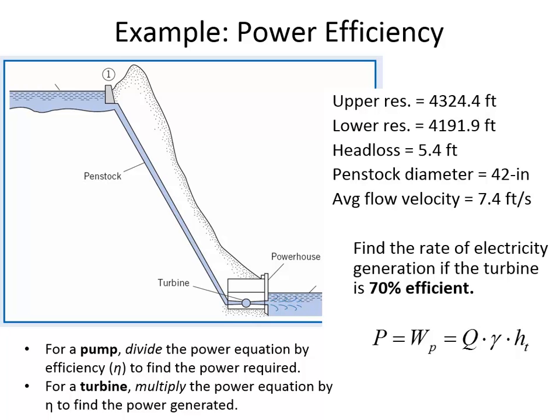The reason it's important is that we're putting the head loss on the right side of the equation. We're saying that the energy at 1 is equal to the energy at 2 plus the head loss. In other words, the energy at 2 is lower than the energy at 1 because of the head loss that's occurred, unless maybe there's also a pump or a turbine changing the energy situation.